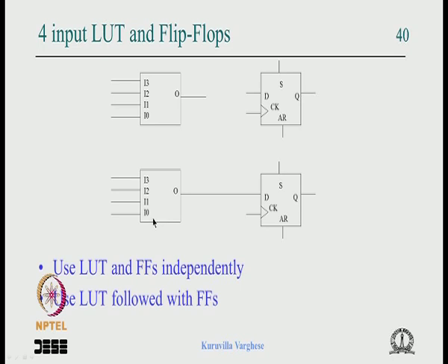So now the thing is that the 5 input lookup table needs 32 locations, okay, because 2 raised to 5 is 32. A 4 input needs 16 locations, so it has 2 raised to 4, 16 locations. So it looks possible because you have 16 locations here, 16 locations here. So how to combine that? You can connect only ABCD, maybe you have a 5th variable.